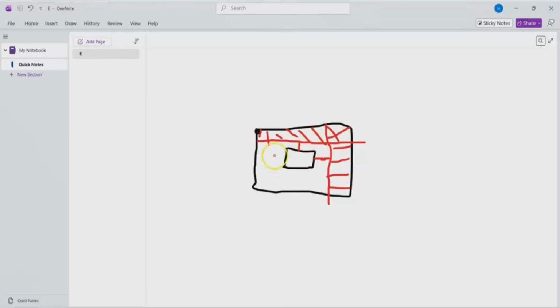So your footing is going to try to shear along this face, or it's going to try to shear also along this face. That is why we say one-way shear. It is shearing just in one face. But the two-way shear, which is a punching shear, is shearing around the perimeter of the column at a distance of d over 2.